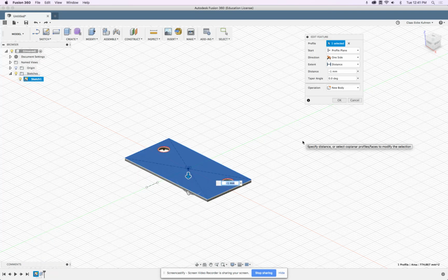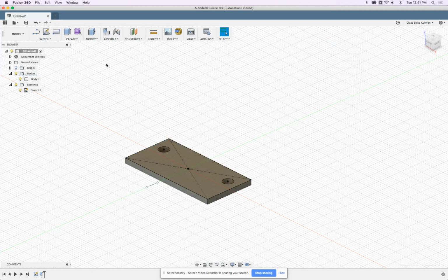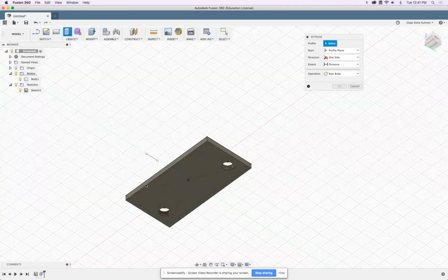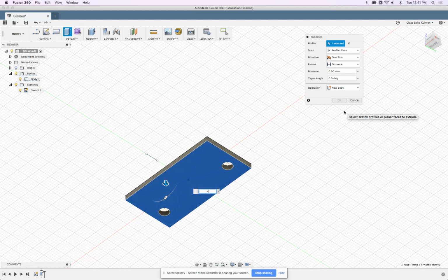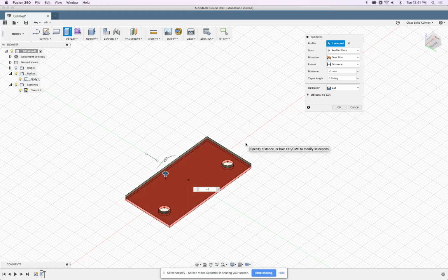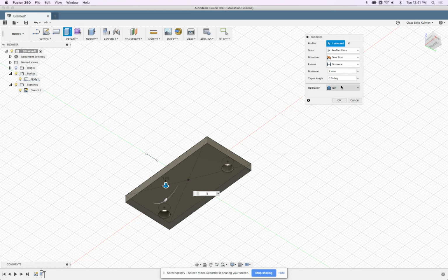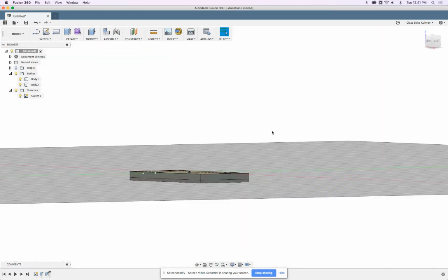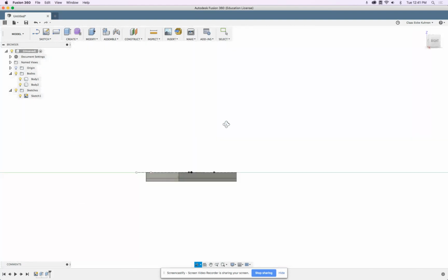And this one now I make -2. I go extrude. Now instead of the sketch, I simply select this face and say -1. Okay, 1 in this case, and say add new body. So you see from the lower face, we're actually extruding it down. Very good.